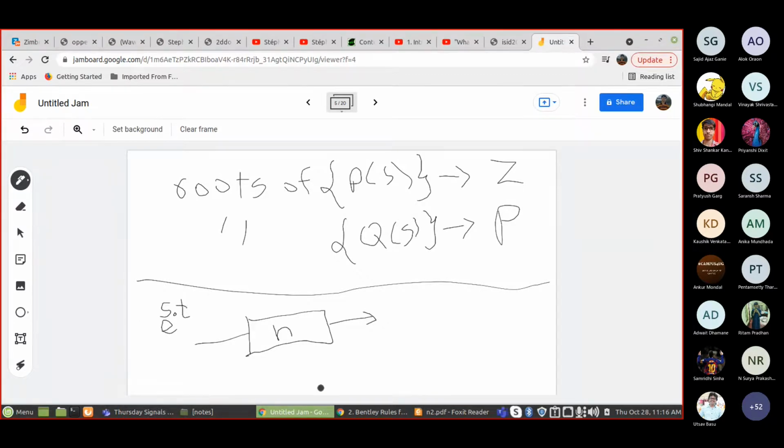Okay, so these are the points where the transfer function becomes zero. Everyone knows that if you give a complex exponential as an input to an LTI system by convolution, what you get at the output is H evaluated at s naught times the same complex exponential. All complex exponentials are eigenfunctions of all LTI systems. If you feed in any complex exponential, you can apply convolution, and then using the definition of the Laplace transform, you can show that this is what you get.